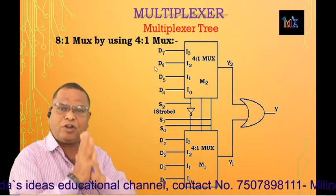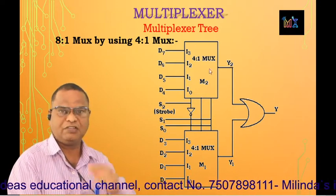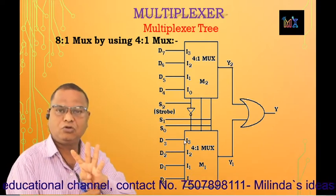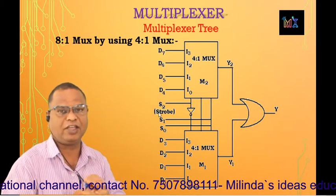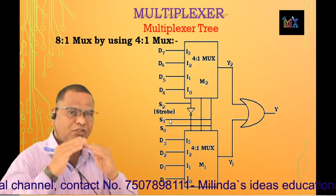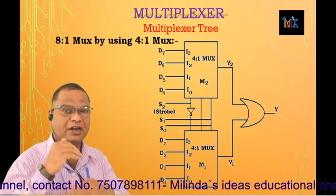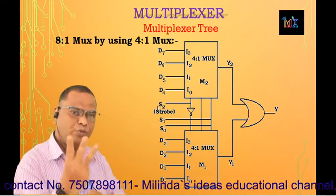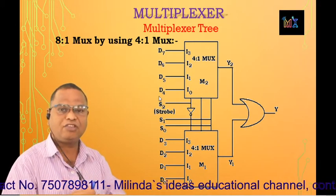Basically it is a 4:1 mux. So as there are 4:1 mux, there are 4 inputs, that is I0 to I3. As there are 4 inputs, there should be 2 control lines or 2 select lines. So S0 and S1 are the control lines. As this 4:1 mux is converted to an 8:1 mux, now there are 8 inputs. So obviously there should be 3 control lines. So how is the third control line achieved?